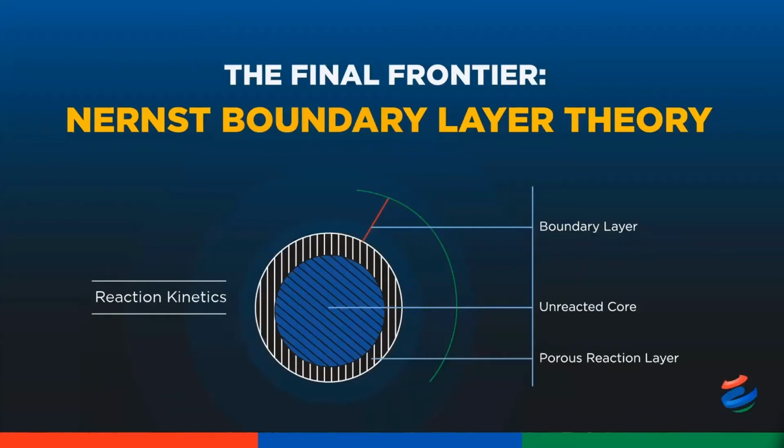The plot thickens as the gold leach reaction occurs in a heterogeneous system consisting of gas, solution, and solids. For heterogeneous systems, the rate-limiting factor is diffusion, which I call the final frontier. This is the final challenge that we have to overcome once the chemical conditions have been satisfied. This is where lances and sparges and injection systems with a low degree of mixing fall short, and where the MACH comes into its own.